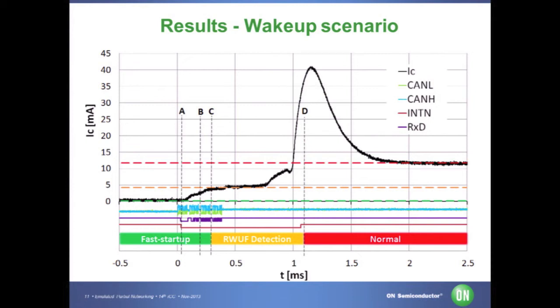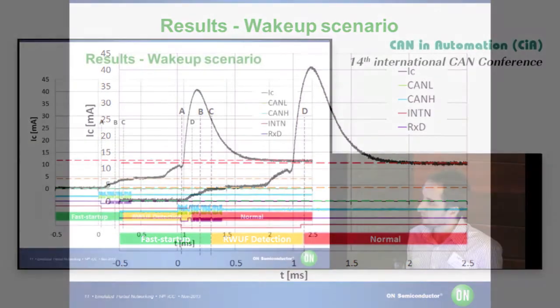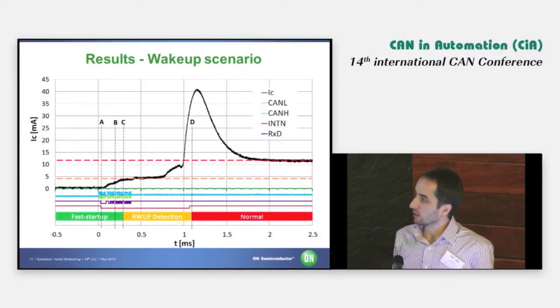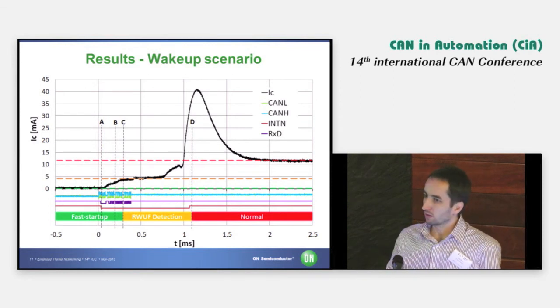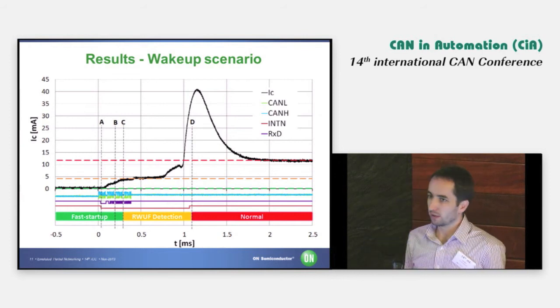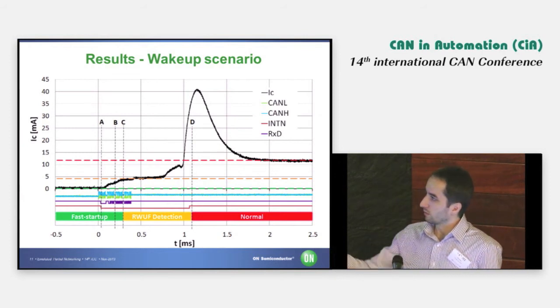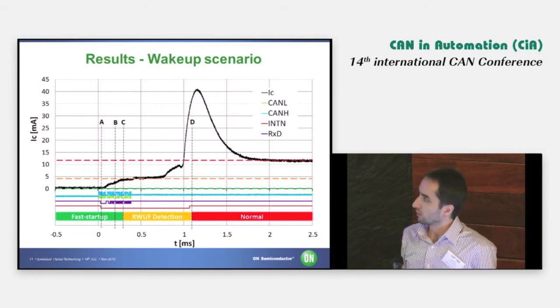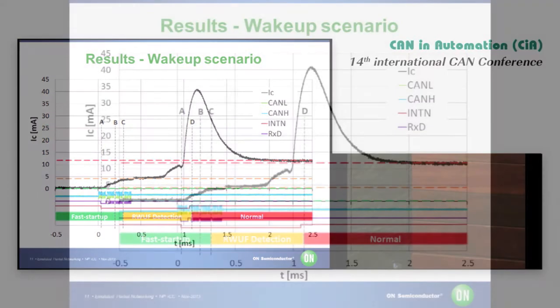Well, it takes, I would say, 2 frames to synchronize the internal communication controller, and then at the 4th frame, it is already able to decode the data to decide if the frame content is valid and if this is really a wake-up frame, and it will wake up, as you can see here at this section.